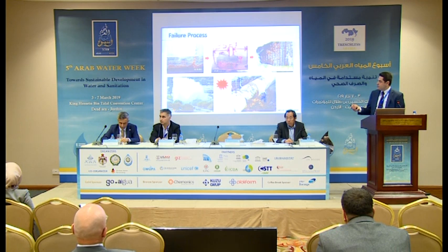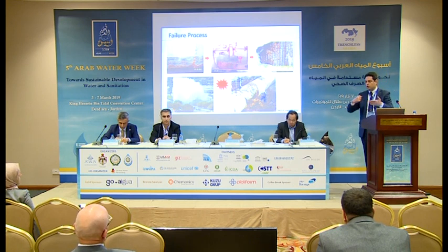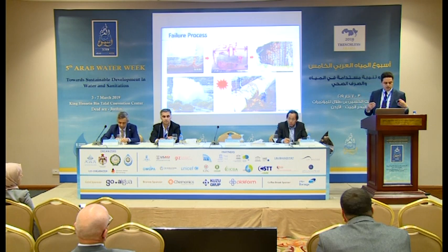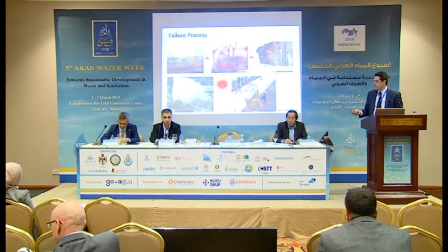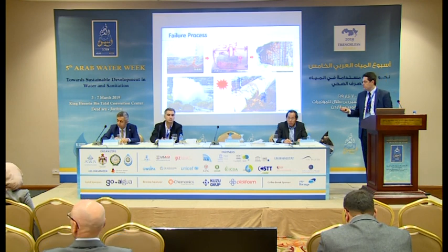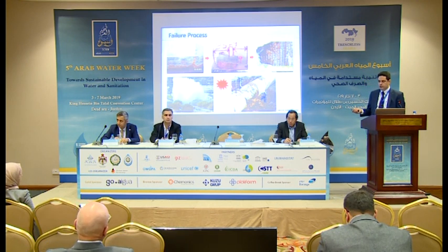They start corroding and start breaking. And as the pre-stressing wires break, the original pre-stress in the pipe is lost. The pipe decompresses, and eventually the concrete core cracks. And after a certain length of degradation in the pipe, this is what happens: the pipe bursts. And this is not an uncommon situation. It happens. Once in a while, we see these on TV. I'm sure you have seen as well.